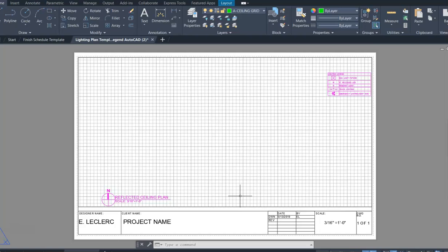When you create the plan, turn your furniture transparency down so the lighting details are more significant, darker. The transparency you want is probably about 70. AutoCAD defaults to 0 transparency, but you're going to turn the transparency in your layer properties. Try the 70. I think the 70 has worked pretty well. For residential and commercial, you can do the same. If you're using a grid ceiling in commercial, you don't have to show the furniture then.